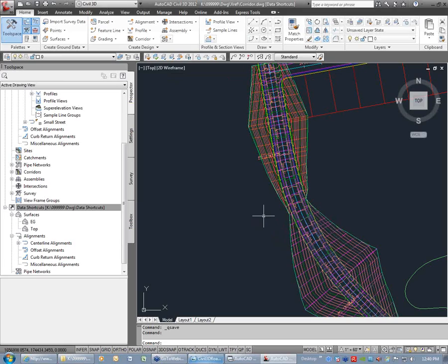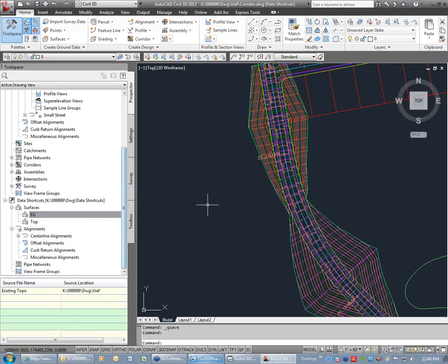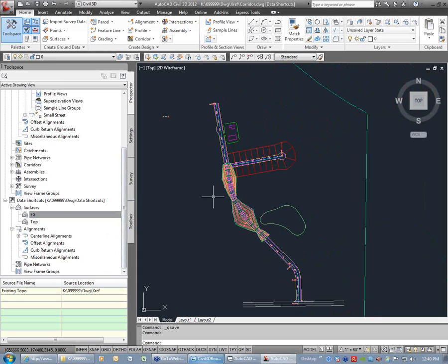So, okay. So you can see here, if you follow some kind of a procedure, every single drawing that you create another Civil 3D entity in, whether it be a surface, some grading, which is also kind of like a surface, a corridor, alignments, if you separate those up from drawings, I can get whatever I need very quickly through this. So I keep the drawings nice and small, tight. One object per drawing is ideal, but that's not always the case. That way, everybody can work what they need to, and they can always pull information to get it in there. Ideally, that's the way it would be nice, but obviously, depending on projects, things do happen.